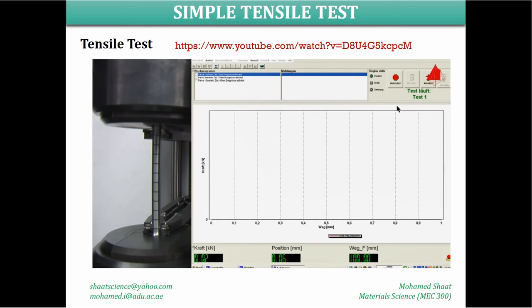During the tensile test, the test piece is slowly and constantly elongated with a standardized speed. The force that the test piece opposes to the imposed elongation is recorded and can be seen at the bottom left-hand corner of the computer display. The material behavior can best be observed in a force elongation diagram. The force F is being plotted upwards on the vertical axis,